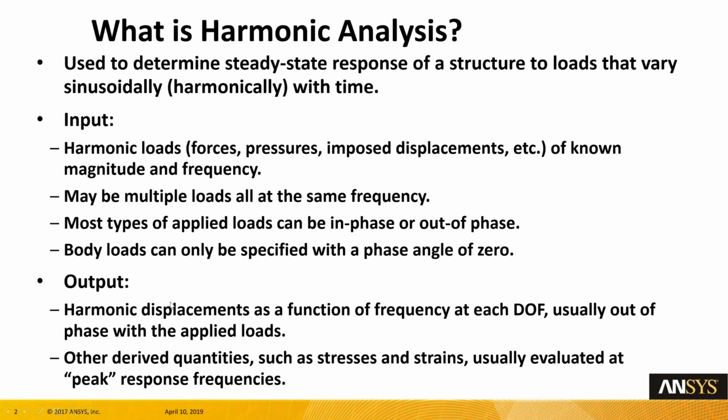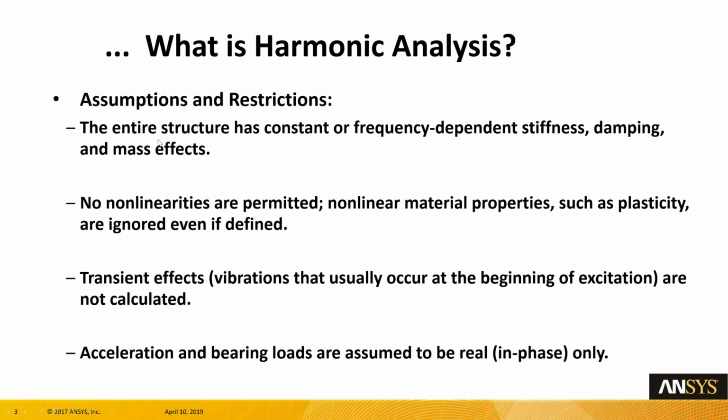Those are the inputs. So what are the outputs? We look at displacements as a function of frequency. And we can also look at stresses and strains. And these are usually evaluated at peak response frequencies. So the assumptions: the entire structure has constant or frequency-dependent stiffness, damping, and mass effects. No nonlinearities are permitted. So harmonic analysis is a linear simulation.